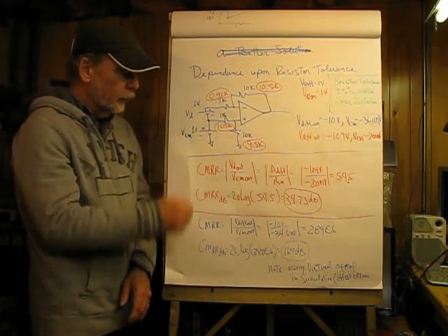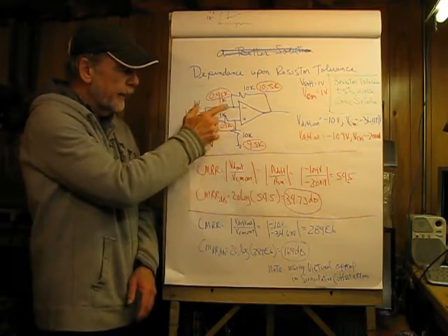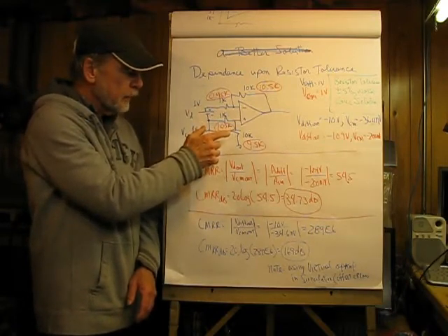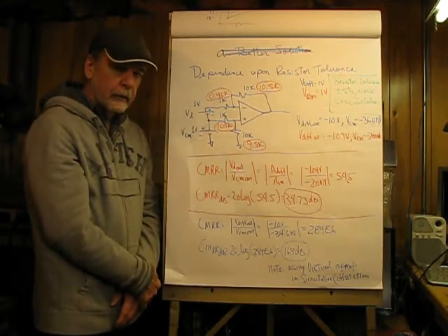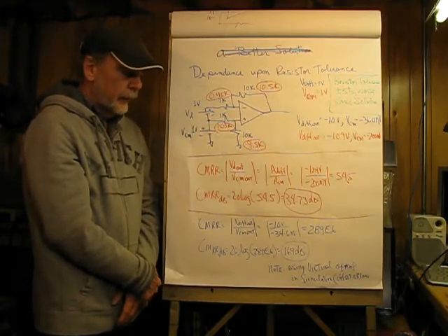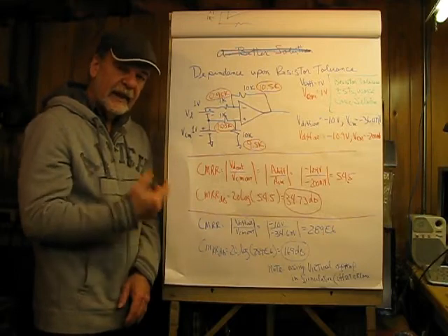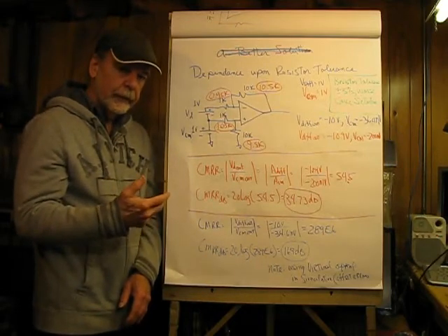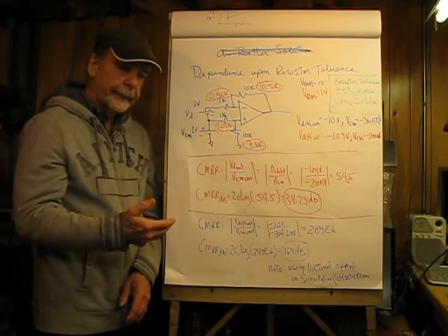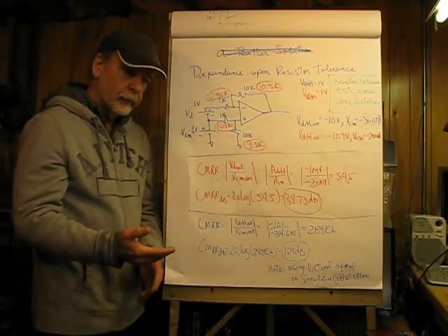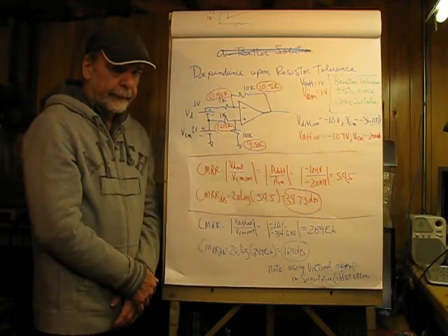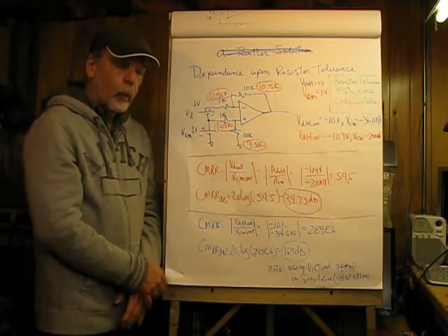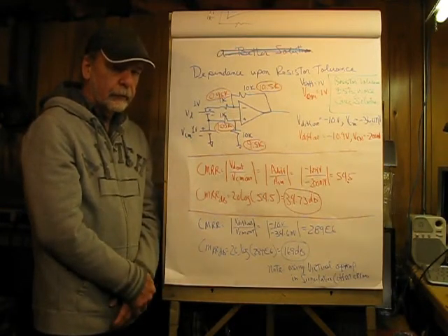I designed a product a number of years ago, and I spec'd these at 0.1%, and then the people that put the board together put in 5%, and it was being fed by a dynamic microphone, which is typically a low-level output, and in addition to that, this had noise canceling, which makes it a little bit lower, and the hum was very noticeable, and we were using a wall supply with plenty of filtering.